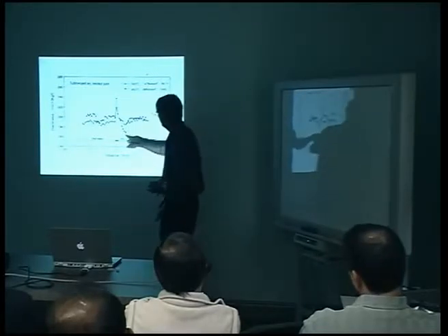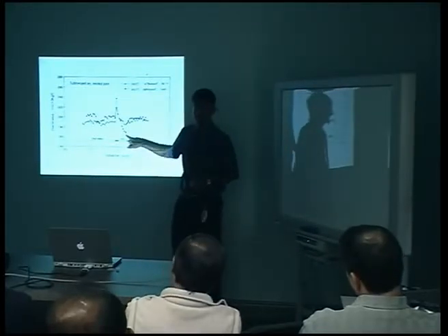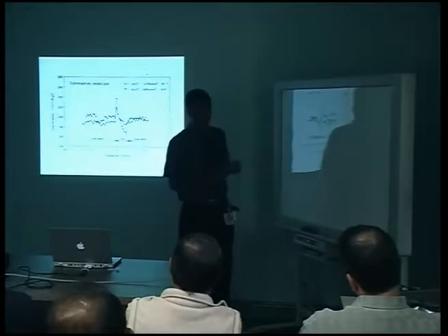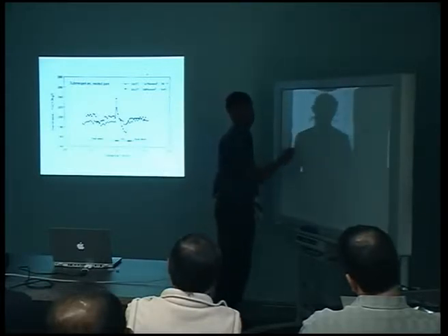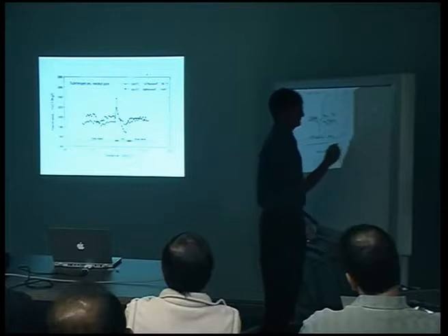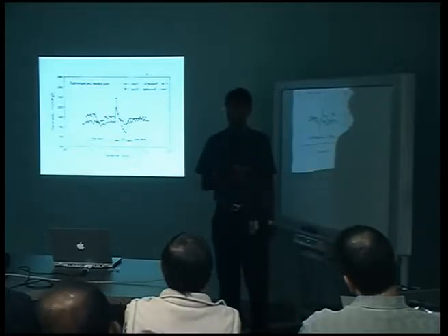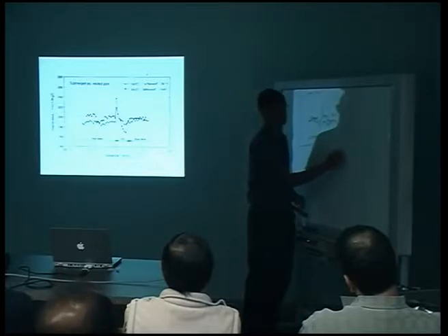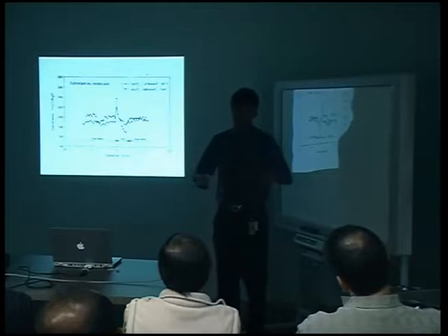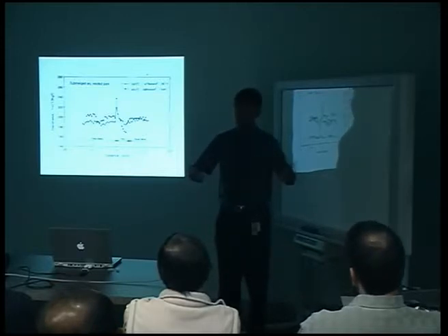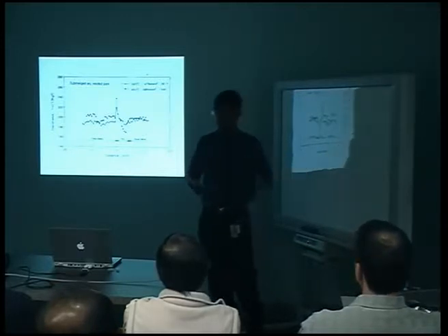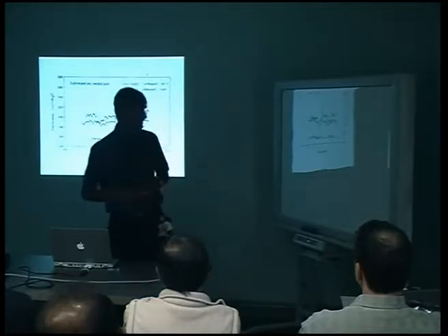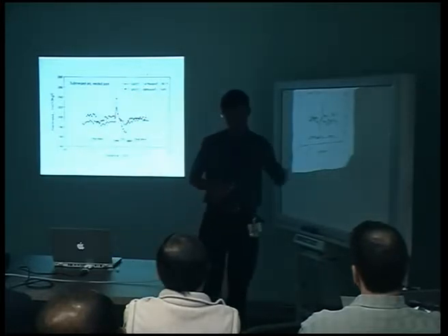So you can see here we've got a soft region. So when there is a stress applied, you tend to focus the strain in this region, and you get failure over here, and that's known as type 4 cracking. And that failure is possibly the most common method of failure in power stations. And as you go to these high chrome steels and so forth, this problem becomes worse.